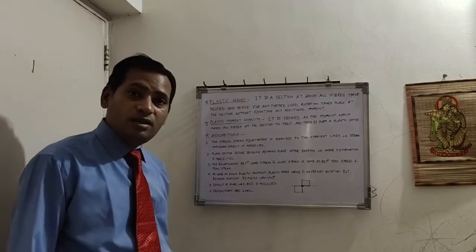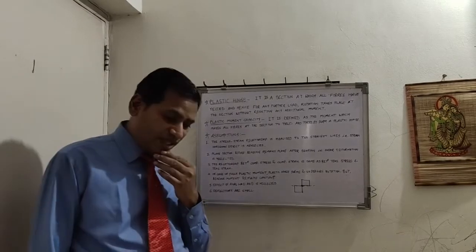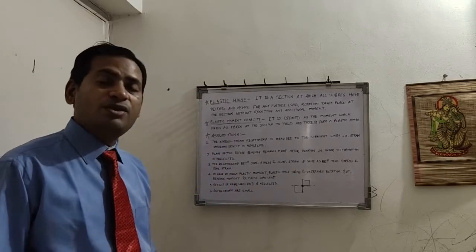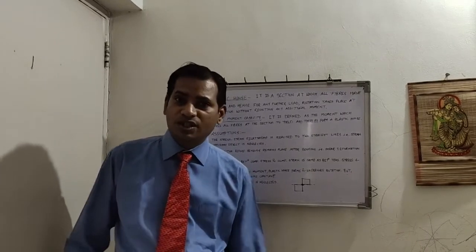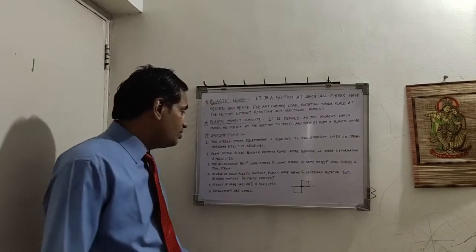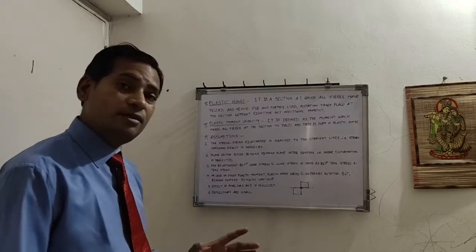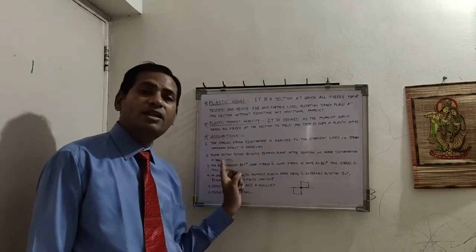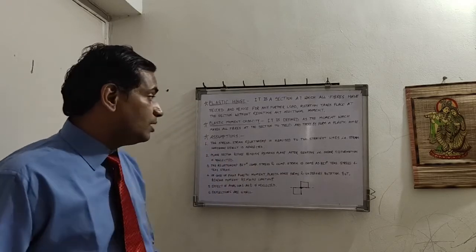Now assumptions. For going ahead, in case of any theory, we need assumptions. Like in stresses in beams or in strength of materials, we have seen a number of assumptions. Many of the assumptions here are also common. One of the common assumptions is the second assumption: plane section before bending remains plane after bending. That is, the meaning of this assumption is that shear deformation is negligible. Then what else is there? There is one additional new assumption.